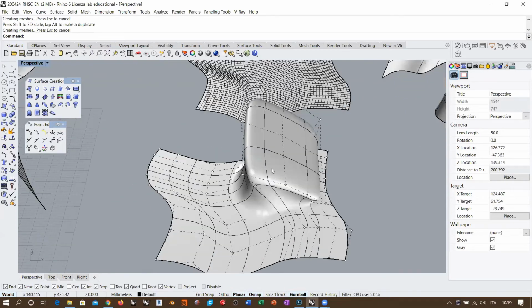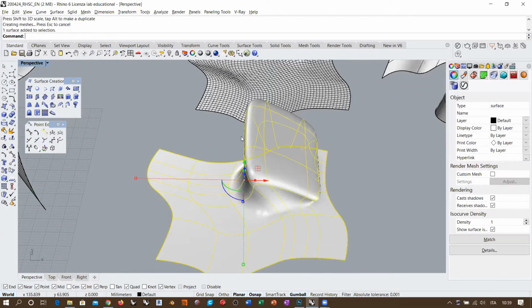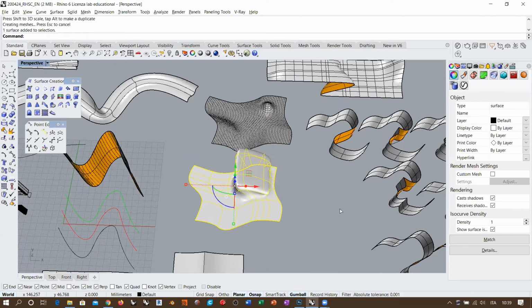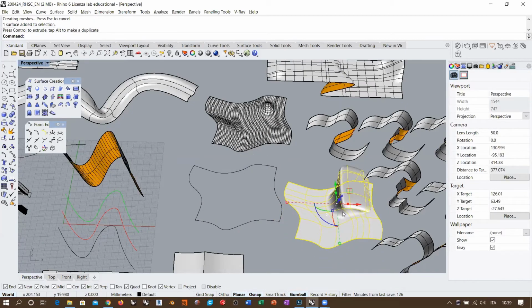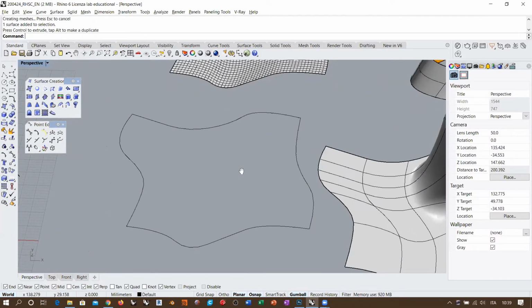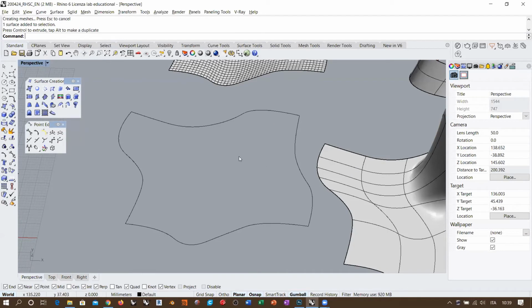And you might think, okay, without considering this extreme situation, where I made this extreme edit, if I try to create a bulge in this area with this command, the surface from network curve, what would I need? Well, what I would need is internal curves, because internal curves become internal knot lines for our surface. So the surface is forced to pass through the internal curves.